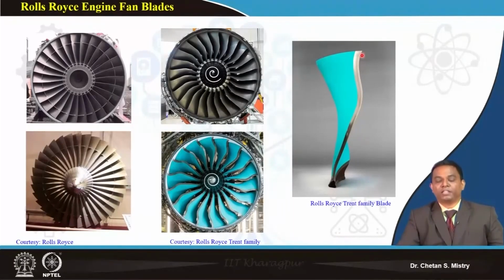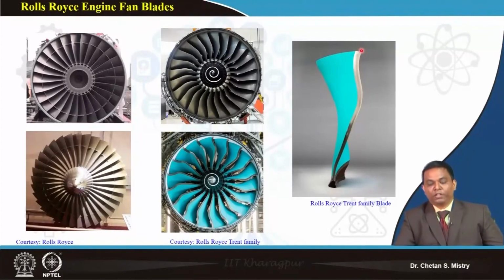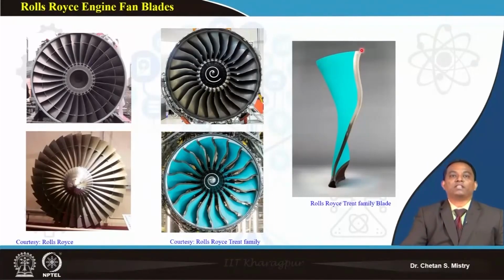This sharp leading edge is there because it has to handle the transonic flow, in the sense of the formation of shock. So this blade will be handling this shock, so that shock will be standing at the leading edge, and that is a special kind of design. And this is a most recent development. That's what these aero engines are doing at this moment.